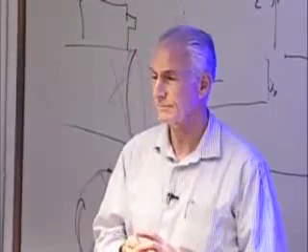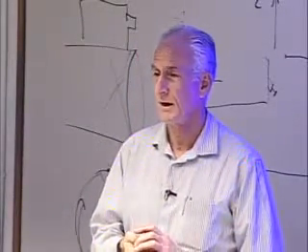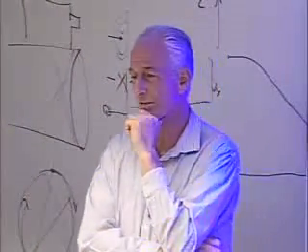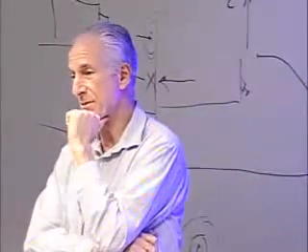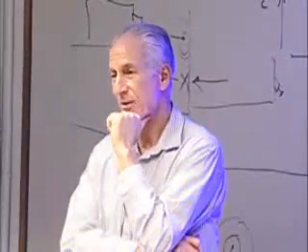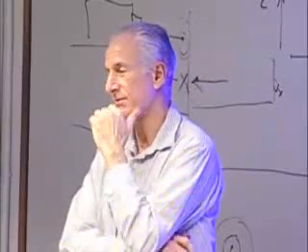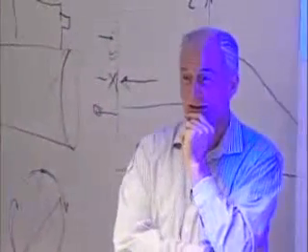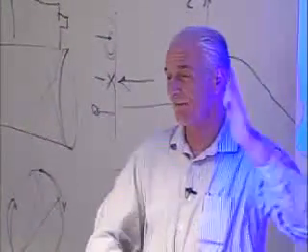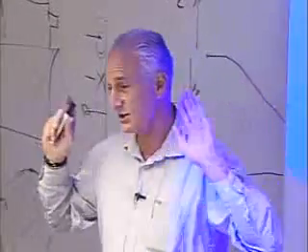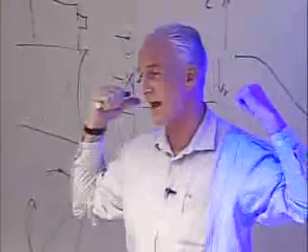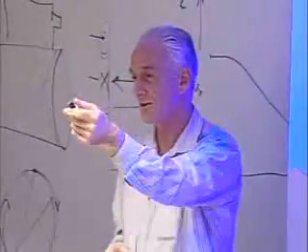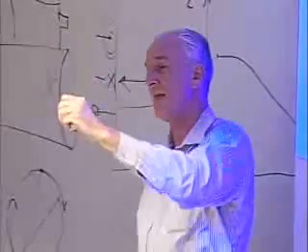Yeah. How does the acceleration compare to the deorbit burn? Deorbit burn is interesting. When the 2 OMS engines fire, they only produce about 1/10 of a G acceleration. However, you've been weightless for a week, a month, 6 months, depending on what your mission has been. The shuttle is accelerating forward, although you're actually going backwards. Okay, but internally, everything wants to go aft.